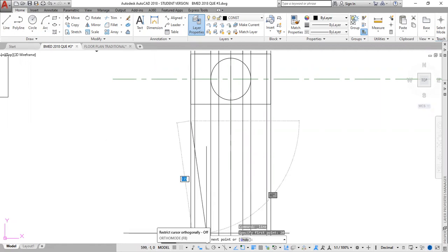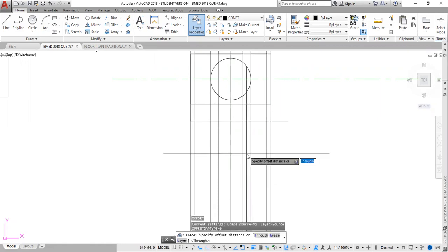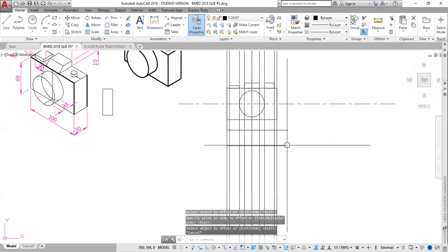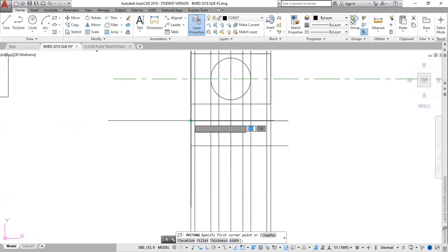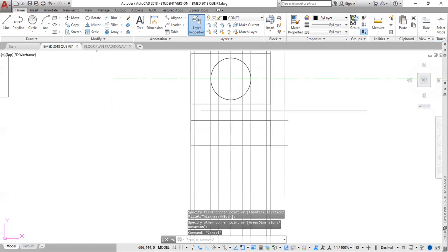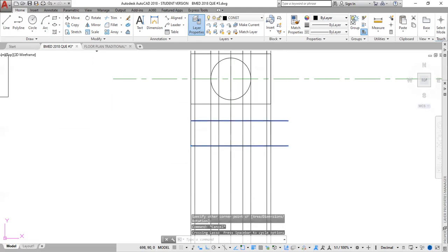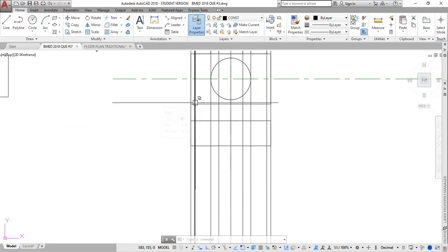Activate my orthogonal mode. Escape. Offset O, enter. Offset 30, 30, enter. Select this, down, escape. So this is now the frame for that. I'm going to use a rectangle to draw the outline for it. Here with that. Escape. Now I'm going to delete these. I don't need those right now. Delete. To get the distance coming down, use object snap tracking.